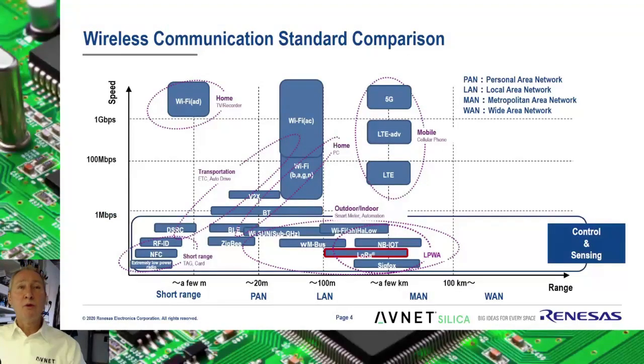In the densely populated field of transmission standards, LoRa is placed in the low power and low data rate field. It operates in the license-free zone, but that doesn't mean it is without restrictions. For instance, you are only allowed to occupy a certain amount of airtime during the uplink and even less during the downlink times.